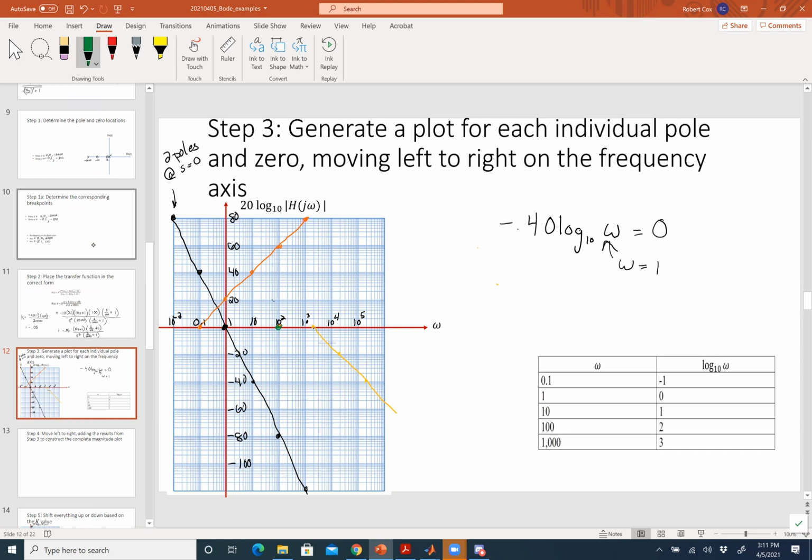All right. Now, this is a 0, so for frequencies lower than the 0, it's what? 0. Frequencies greater than the 0, it's what? 20 dB rising. So that means at 1,000, it's at 20 dB. At 10,000, it's at 40 dB. At 100,000, it's at 60 dB.